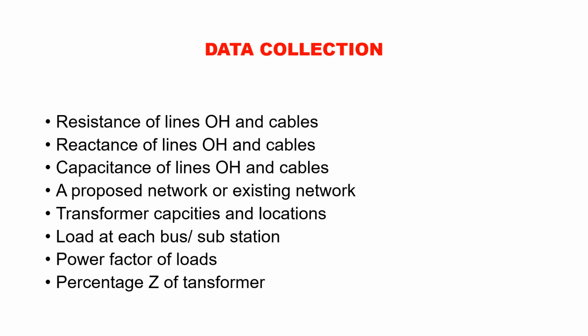If you have 10 lines or 50 lines and you remove one line at a time, then you will call it n-1 contingency. N will mean the total number of that item. Suppose you have 100 transformers or 50 machines, and you are taking one machine at a time, you will call it again the n-1 contingency of the generating plant or the transformer or the line. So one by one you conduct the study, taking out important lines you select, and there can be two cases.